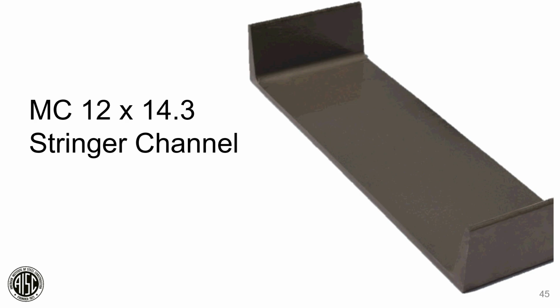I also want to talk about a unique channel shape, an MC12 by 14.3. It's a stringer channel. Now this product was developed to act as a stair stringer. Now the unique property of this product is the flange is 2 1/8 inches wide, which means that you can actually take a post from a handrail and weld it to the top of this flange all around. You wouldn't have to crimp it to fit on a smaller flange.